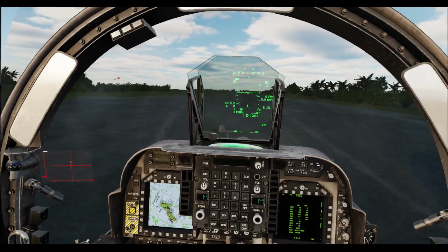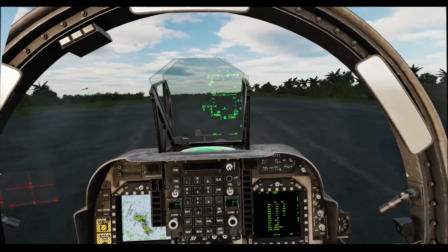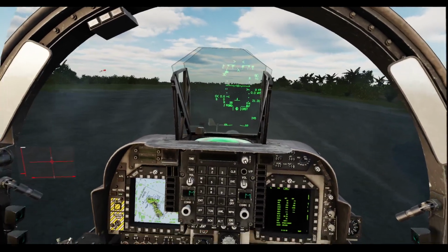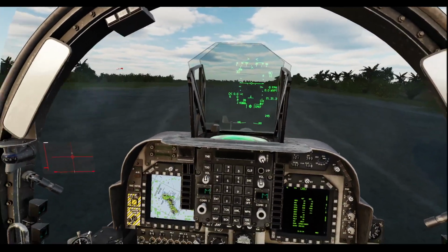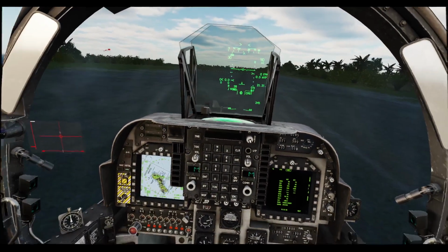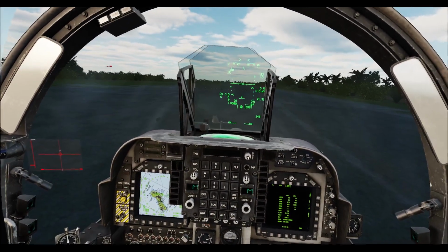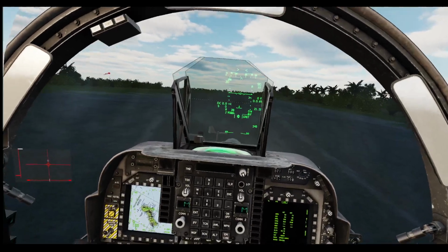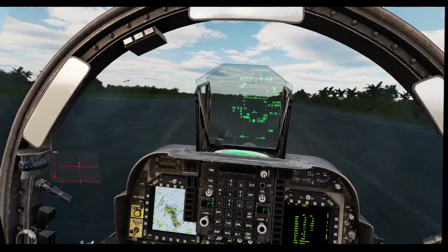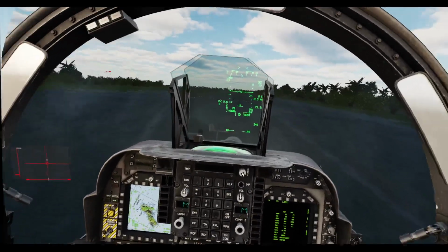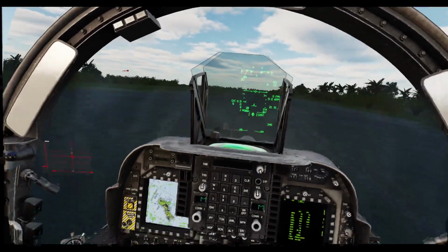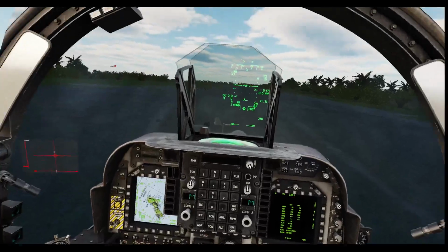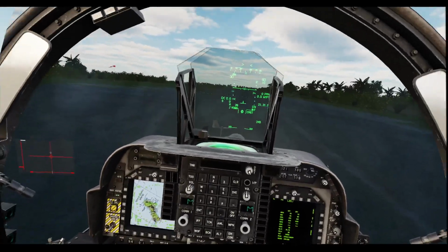So the big difference between this and, say, if you're doing it at a large airfield where the runway is quite long, let's say Anderson, is that after you do the capture attitude technique and do the acceleration, the accelerating transition to wing-borne flight, with the VSTOL assessment specifically, you leave the nozzles at 25 degrees.